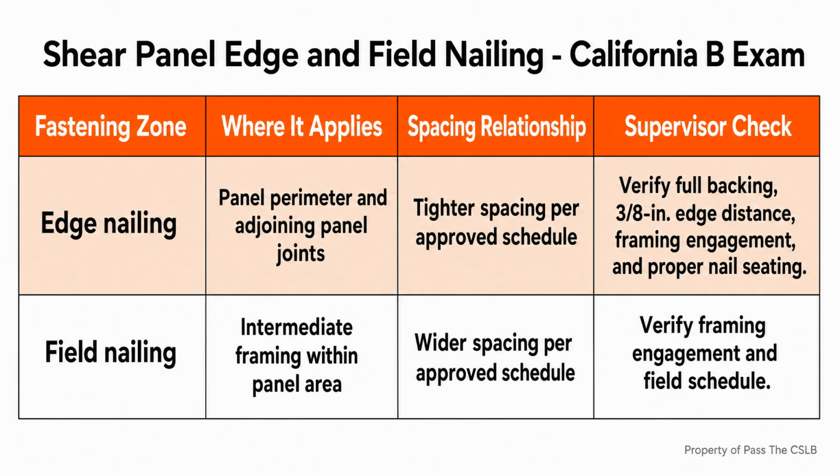I would rather see a superintendent verify the backing first, then verify the edge line, then verify the spacing, then simply count nail heads from the exterior.